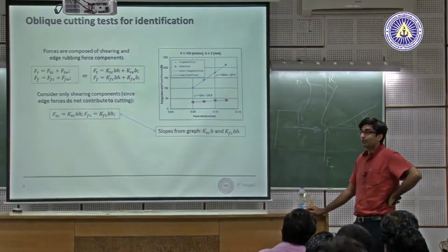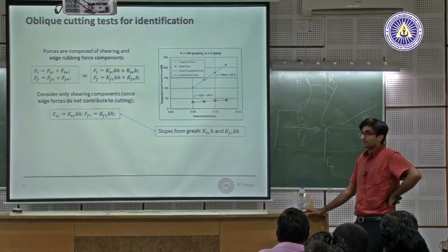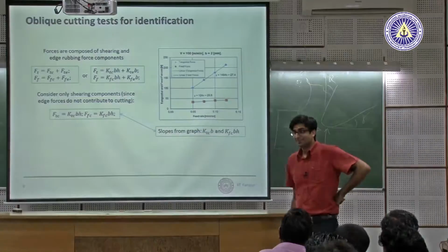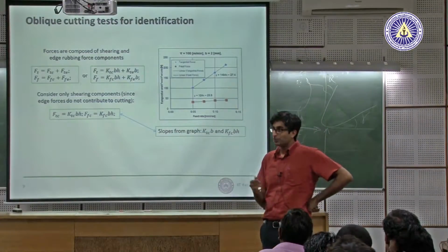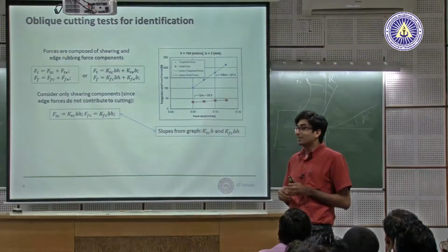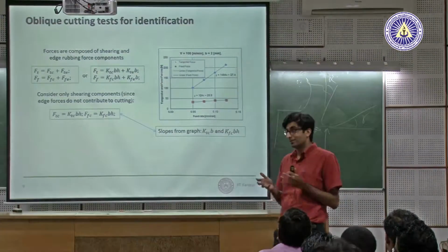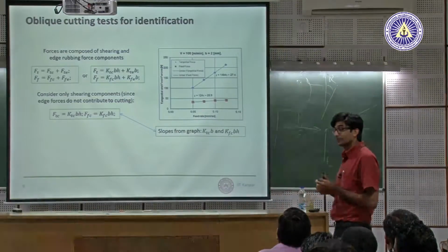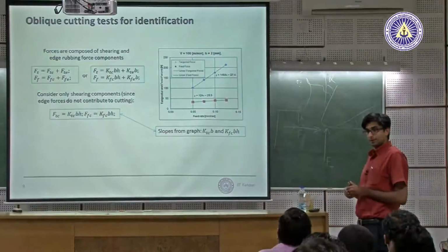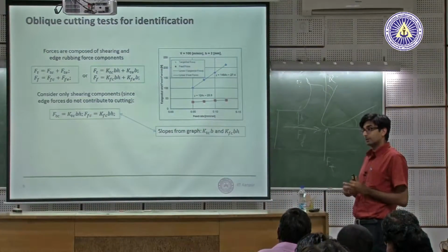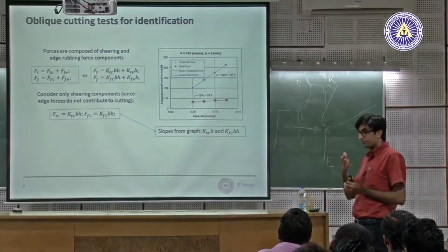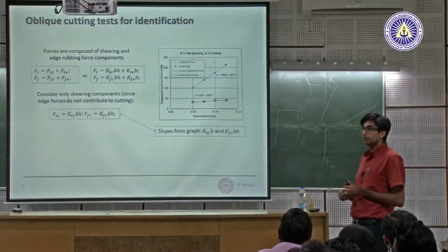There are 2 values of cutting speed, 300 to 400. You can average it, because all this is an approximation. It gives you some idea. Otherwise, you are in the dark. You don't really know how it is going to behave. So typically, you take low speed, high speed, and maybe even the middle. You measure in all 3 parameters, create a nice model, average all 3, and that's the coefficient you use.